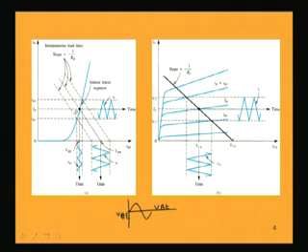As IB is increasing from its DC value, correspondingly IC will also increase. Initially when there is no signal, the DC value of that IC is capital I capital C, that is this point.